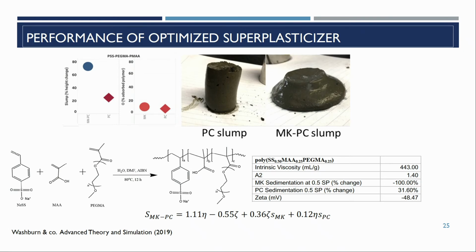The interesting thing that we observed was that if you took the same polymer and put it into just pure Portland cement, it didn't seem to do much plasticizing. There was something about the way this polymer was interacting with the metakaolin parts that was most efficacious. There was obviously some plasticization. You still had 85% Portland cement, but the bump seemed to be very specific for metakaolin.